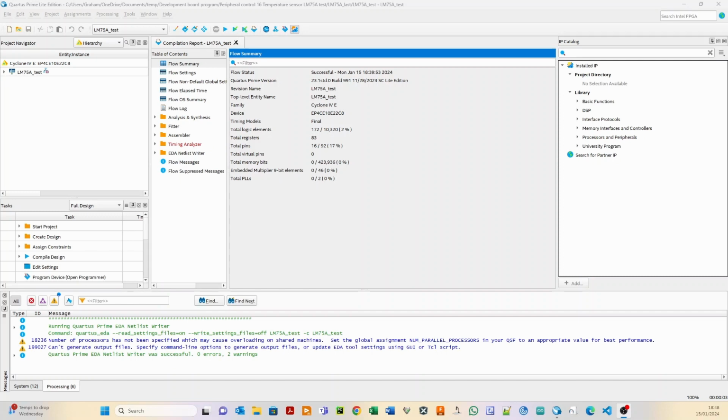When you get the board, the flash has a program in it that flashes the 4 LEDs in a sequence. But once you've uploaded a new program and turn the power off, it forgets any new programs that you enter, unless you burn them into the flash. And this is how you go about burning them into flash.